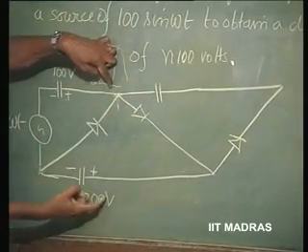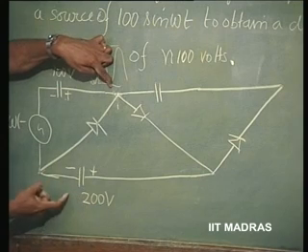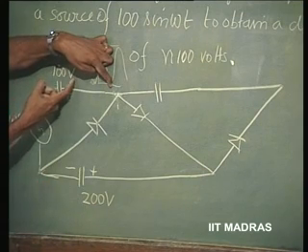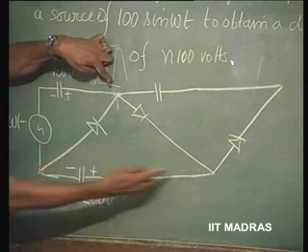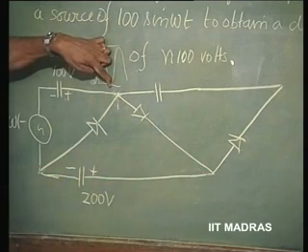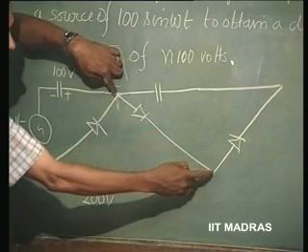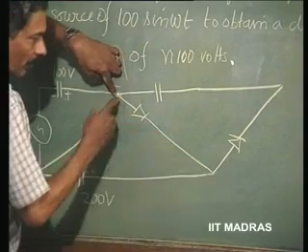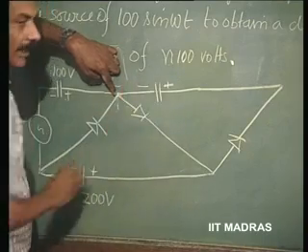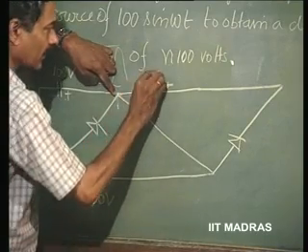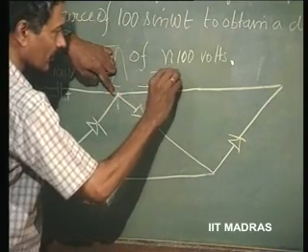You see here 100 volts positive, 200 volts positive minus 100 volts negative. So, essentially from here to here we have 100 volts positive in this direction and 100 sin omega t, and therefore, this effective voltage is going to be more positive than this, and it will charge the capacitor to again the peak value that corresponds to 200 volts.